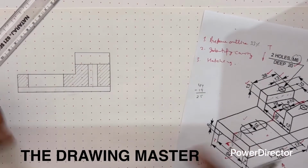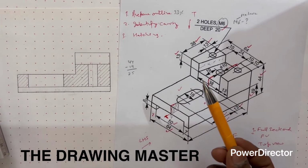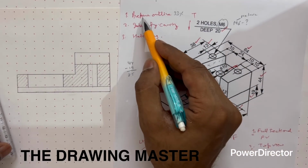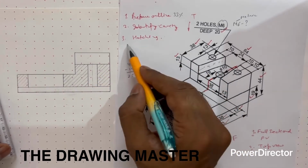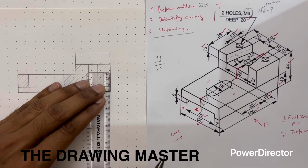So let's draw the top view of the object. For top view, simply the very first step is to take the projection. And here you have seen, with the help of these three steps, prepare outline, identify cavities, and then hatching, we can do the sectioning in a very simple manner. So let's draw the top view.